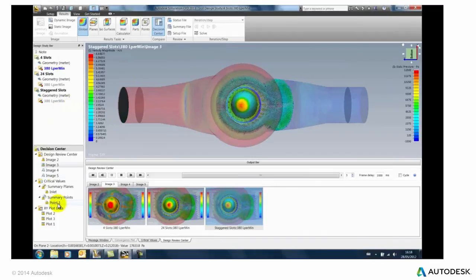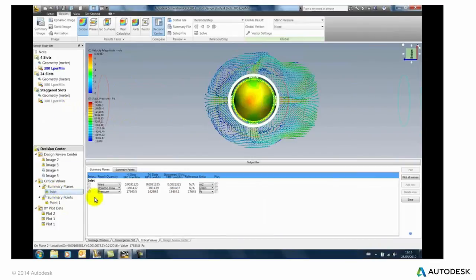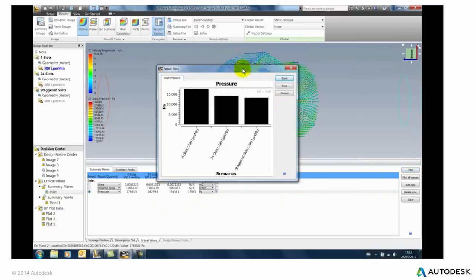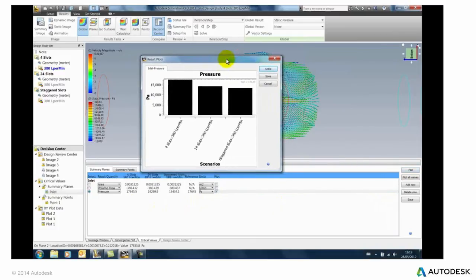You can also check things like effects on pressure drop through the different designs. So although we've made the flow more efficient, have we affected the pressure drop? And we see that with the third design on the right, the pressure drop is actually lower. So not only have we improved the flow, but we reduced the pressure drop, which means a higher output for a given flow rate.